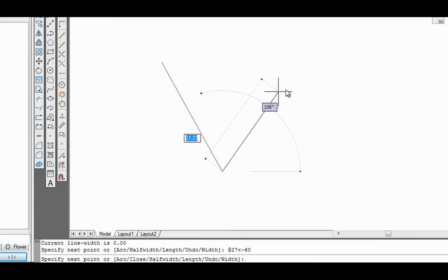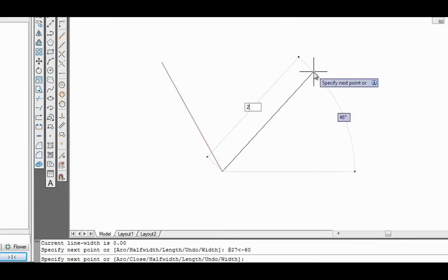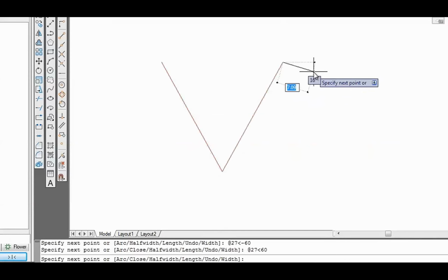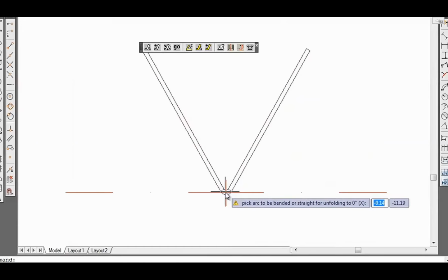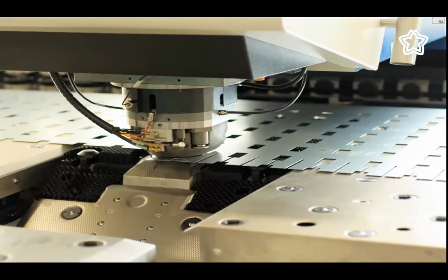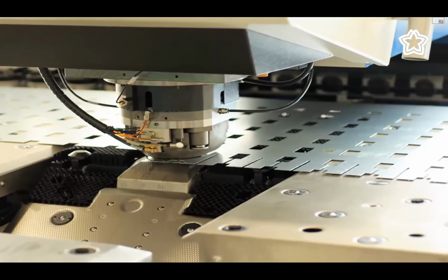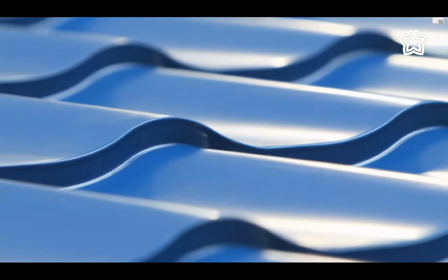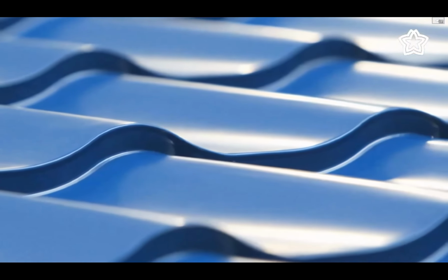The starting point is to draw a cross-section where the required radii, thickness and dimensions are applied. The minimum radius for bending is decided by the thickness and the properties of the material. Here, it is also decided if the profile will be punched or pre-cut, and if it needs to pass through more preparatory stages before roll forming.